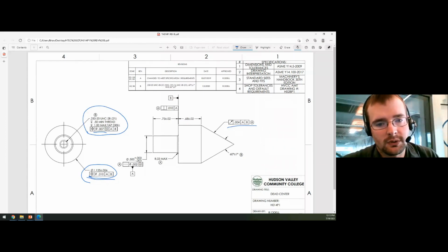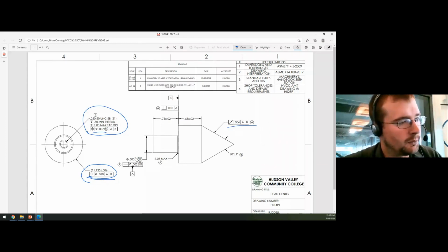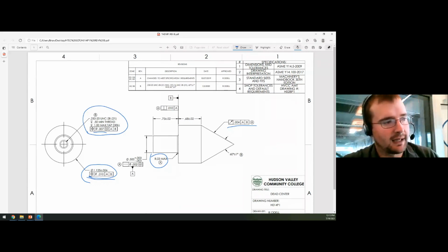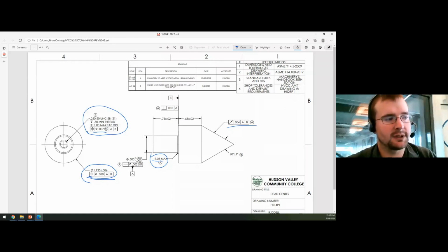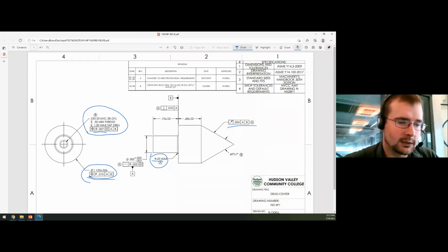These are things that we really focus on, and we'll go from R30 max and we'll start to tolerance that at like plus or minus, and they can see that if this is a range that doesn't match an insert radius that we have in stock, we have to buy another insert, and why that makes a difference. And that's real important. Sometimes it's not so much the big concepts, it's the little ones.